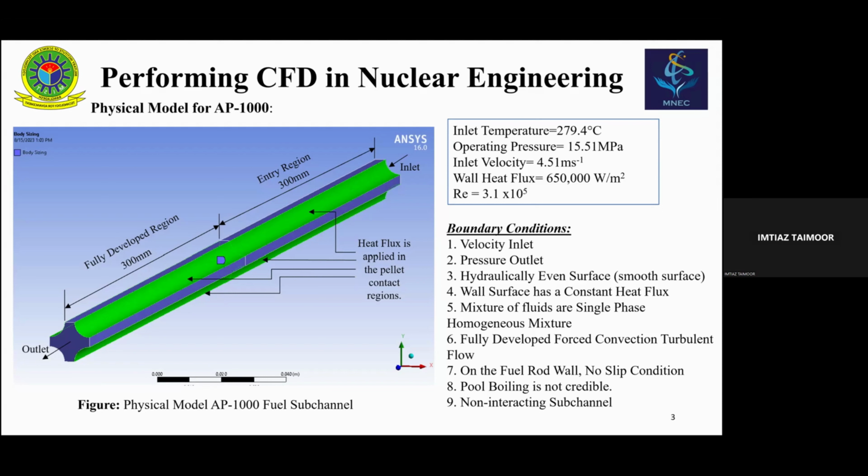I didn't do that because whenever the flow is entering through this inlet into this subchannel, we need to give a certain length to the flow so that the flow develops fully. And if we let the flow develop fully, then we can have the real and accurate properties of the flow, or the flow dynamics. Have you got my point? I think this is a bit difficult.